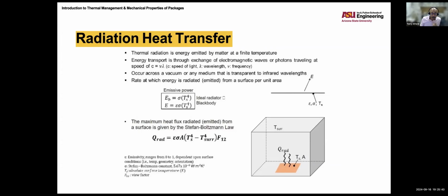But in this case, we'll have the sum, just like we had previously, for one path, sum for the other path, then add them in parallel. In a similar manner, that's what we did previously. Now we have the bottom. We just do the same calculation, but we take into account the bottom convection, the substrate, and the interconnect layer.